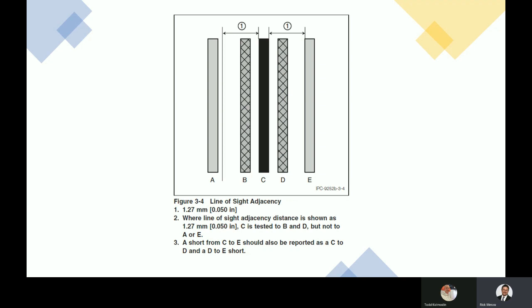But if you have a signal layer and it goes through 2 or 3 layers, and there's another trace that runs above it on the layer above. So if you have a trace on 12 that's running one direction and a trace on 11 that's running another direction, technically they wouldn't be checked for a short unless you turned on something called vertical short, where it's basically looking at Z. So it's looking through the board itself, same window size. It takes into account material types and different things, but you're going to look for a short between layer 12 and layer 11 if they're within that window size again. If there's a short there, it'll detect it.